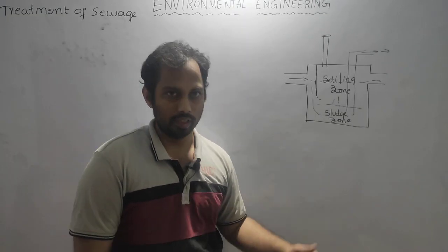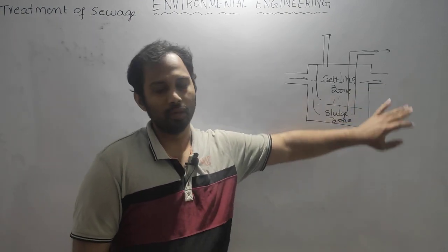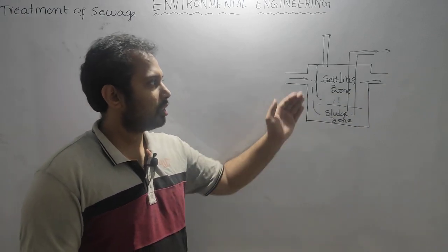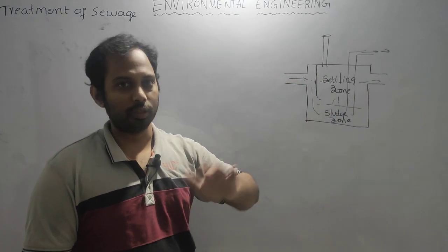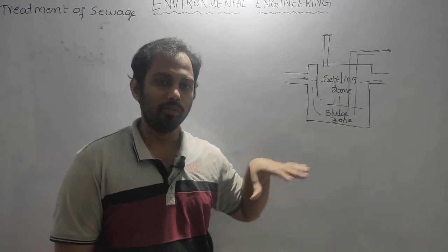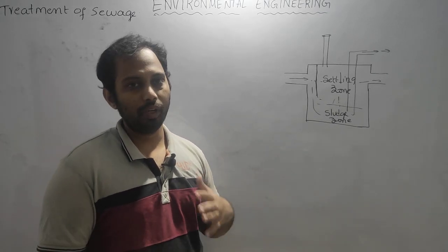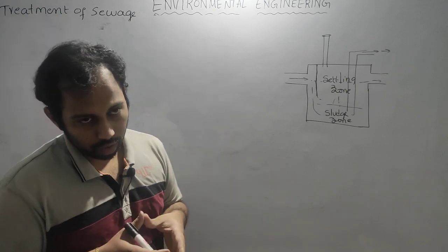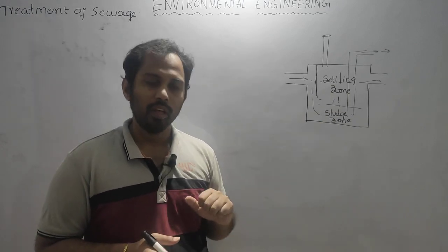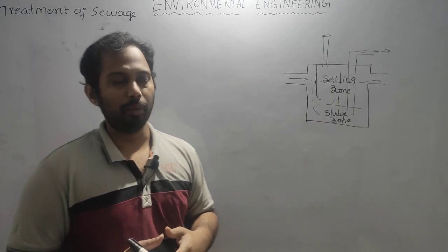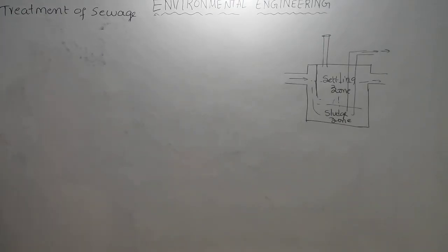So in those cases, when the BOD of the effluent coming out of the septic tank is considerable, we send that effluent to a soak pit, drain, dispersion trenches or leaching cesspools. All these mechanisms are available to take care of the effluent. So the septic tank can be used for household activities, and also for a group of people in a community, depending upon the drainage availability in that locality. This is how the septic tank works.